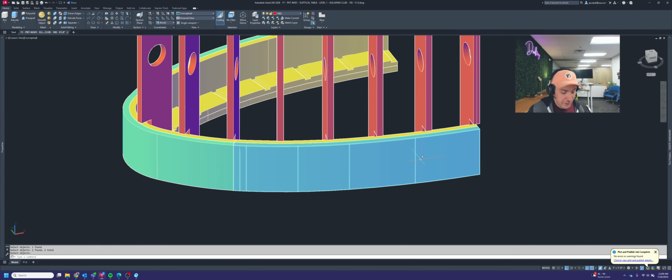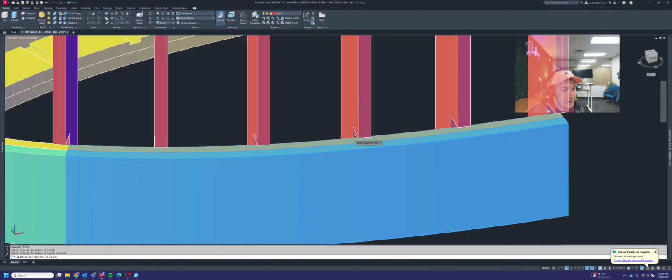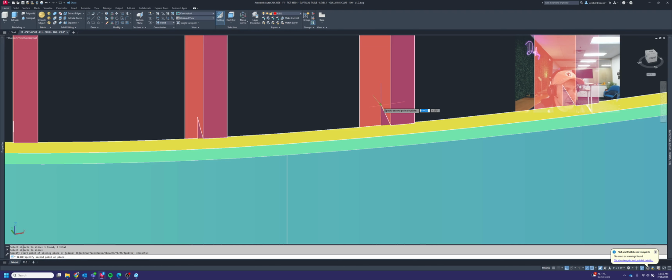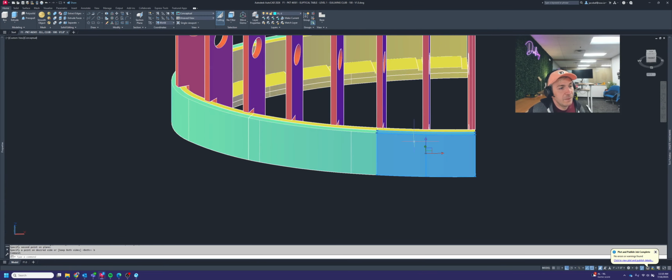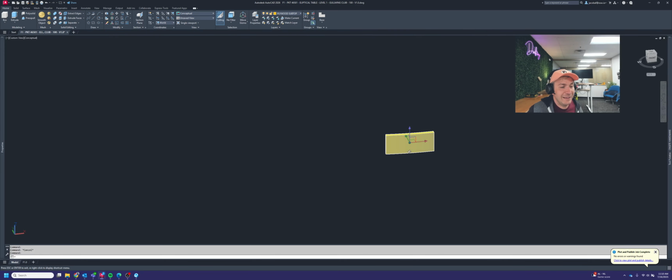And then what I want to do next is find the next rib that I'm going to use as a slicing plane, which should be the inside of, I think it was this one. 1, 2, 3, 4. Oh no, I'm sorry, it was this one here. I was going to use this one here. So we're going to highlight the base trim and the substrate again. And I'm going to click this point and this point here. Use both to keep both sides. All right. And this one did not slice through that side, so that's great. And it's a check. That did not either.